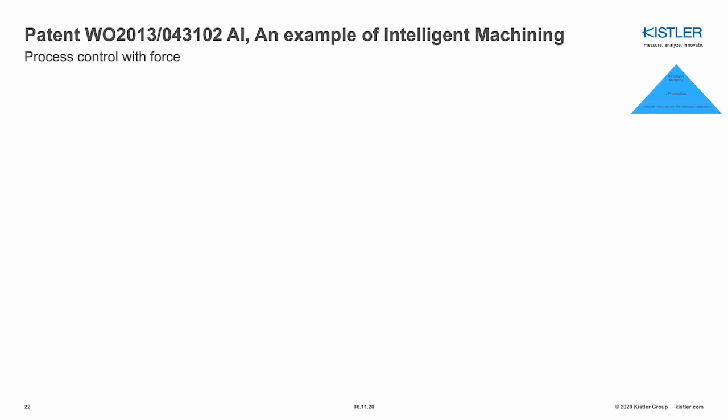Now let's move to the last step here, if you remember: intelligent machining. So we need to make the offline measurement of your machine as the first step, then the online measurement during the process with the right sensor, build the correlation, and then make the control loops.